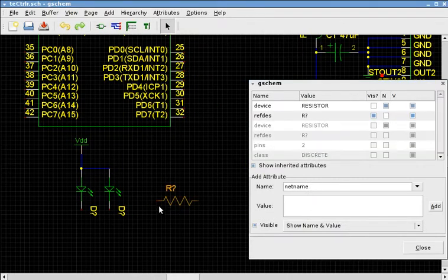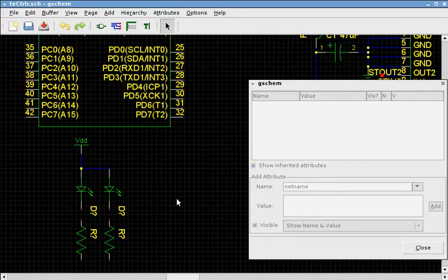And we'll just put here, and then use ER to rotate a part. ER can also be used to rotate a part before you put it into the schematic. So we'll do that and put another one here, and now we have an extra one here. When you have an extra one, or when you need to select a component, you can always use the shortcut key lowercase s to select the select tool, and then you click on the component and you press the delete key to get rid of the extra component that we don't need anymore.